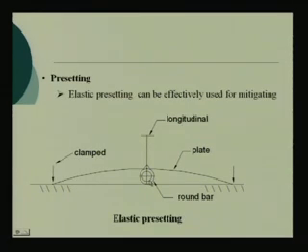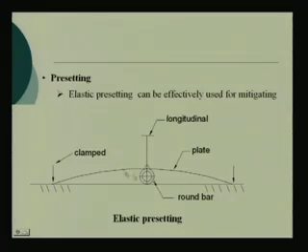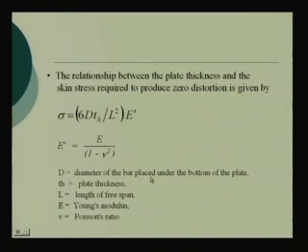So, when a stiffener is welded, you have angular deformation. So, there it is being pre-bent with the extent of deformation that is anticipated by putting a round bar below, and then the welding is done, right.